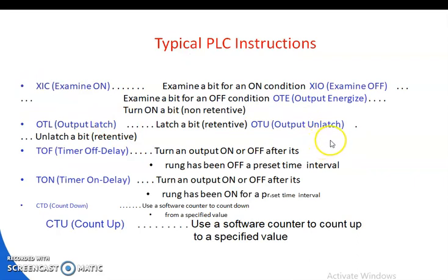While we go through the PLC subject, there will be much more idea regarding this. XIC means examine on: examine a bit for an on condition. XIO, examine off: examine a bit for an off condition.